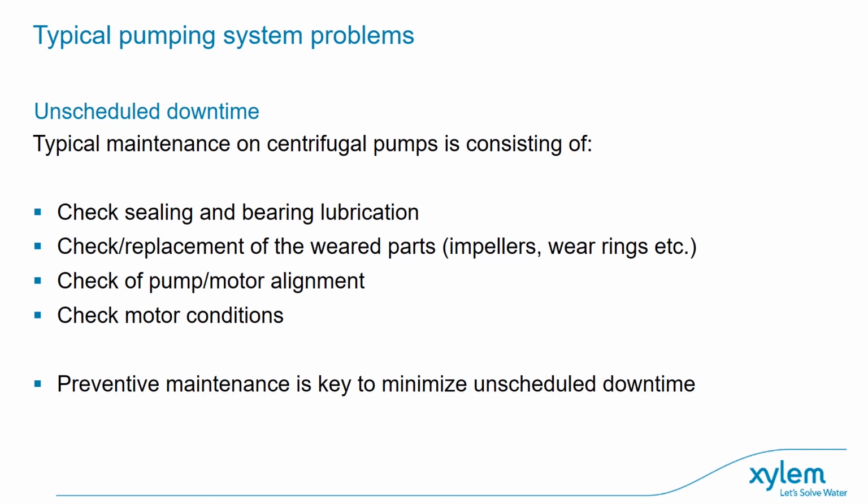Basically, all this can have a very varied time frame when it comes to mean time before the different actions. When we are speaking about centrifugal pumps, we are talking about 6 months, 1 year, but it heavily depends upon the single application.